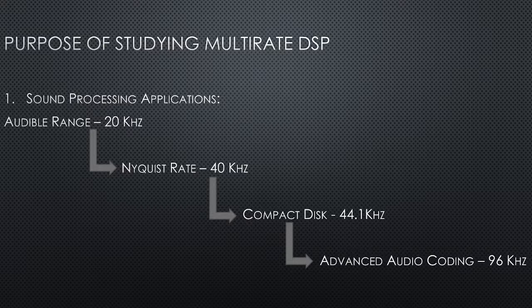When we talk about a microprocessor, okay, a microprocessor has a certain speed with which it processes data, but it's not necessary that all the peripherals interacting with the microprocessor are working at that speed, right? For example, a CD drive, which we hardly use nowadays, or a hard disk, they read and write data at a particular rate, whereas a microprocessor works on a different rate.